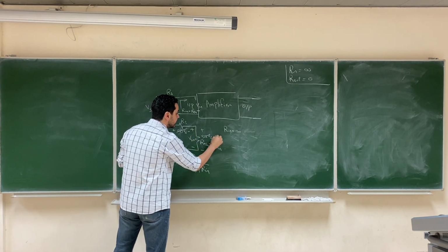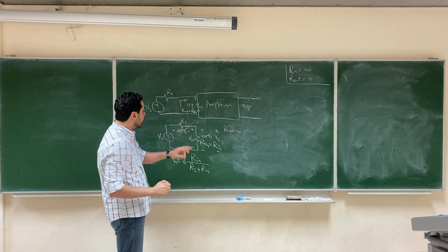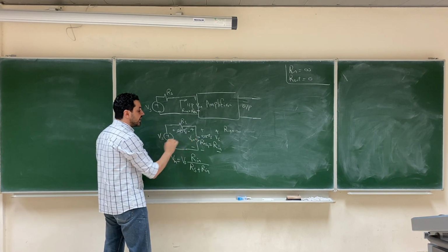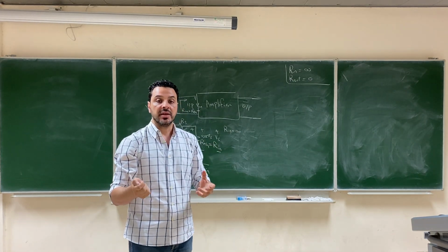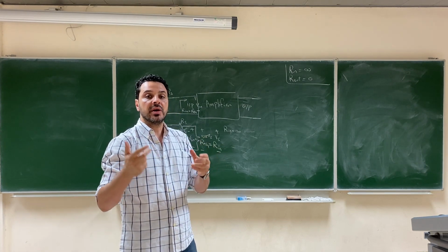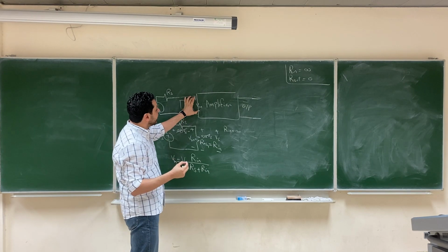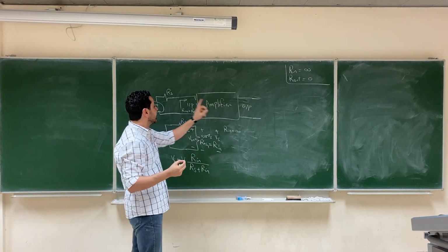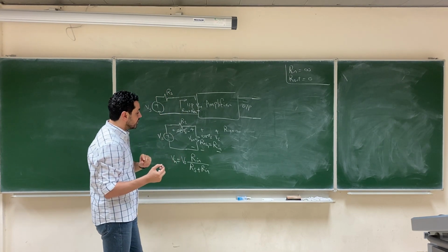So all of Vs will go to the input of the amplifier, while Rs will not take any voltage across it. This is the perfect situation, because all the source voltage will go to the input terminals of the amplifier and be amplified, and nothing will be wasted on the internal resistance of the source.